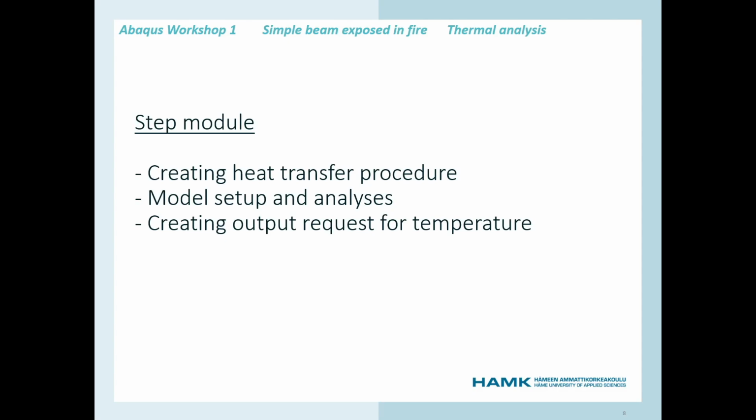step module here. In this module, this is very important because we have to define what we are going to do, what type of analysis we are going to follow. So in the step module, we assign the proper type of analysis, and the step is needed in order to create different interactions and the loading for each step.